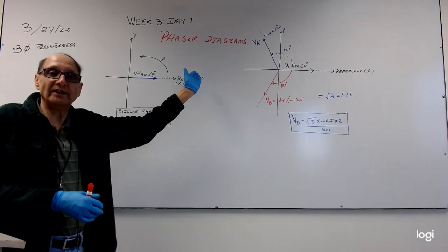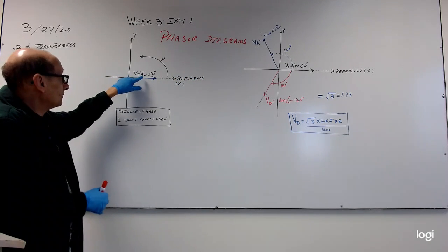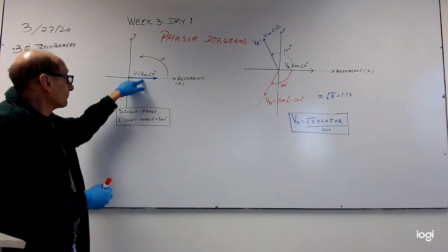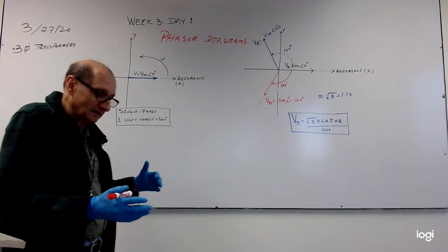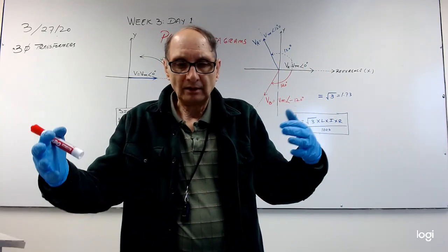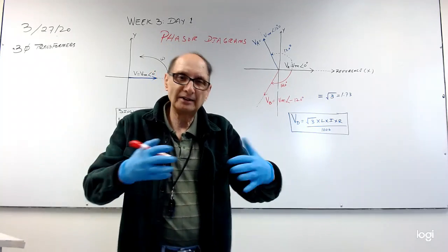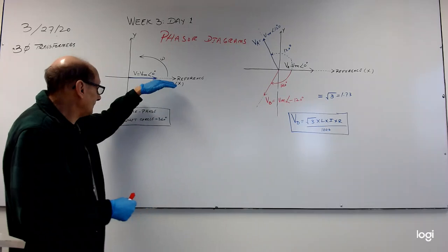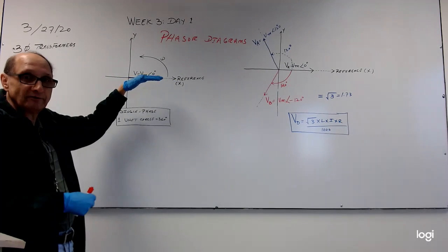There is no phase shift over here. So V equal to Vm, which is the magnitude, at an angle of 0 degree, because when it comes to single phase, whether it's two-wire or three-wire, there is no phase shift between these two. So that's why the magnitude is going to fall on x-axis, which is reference point.